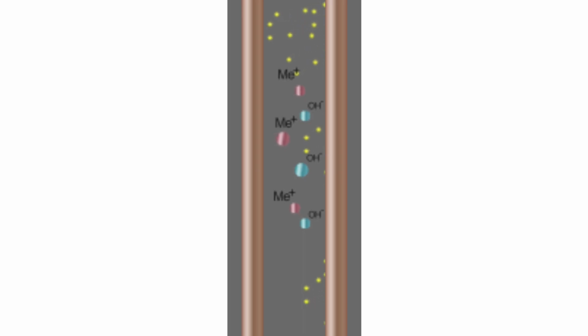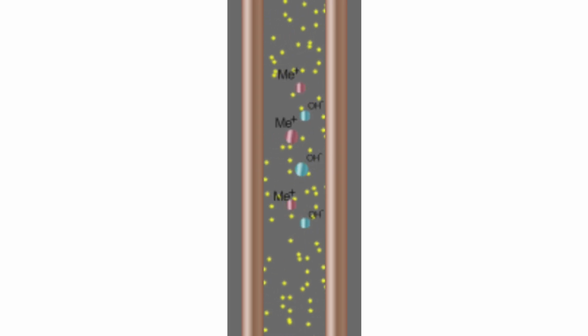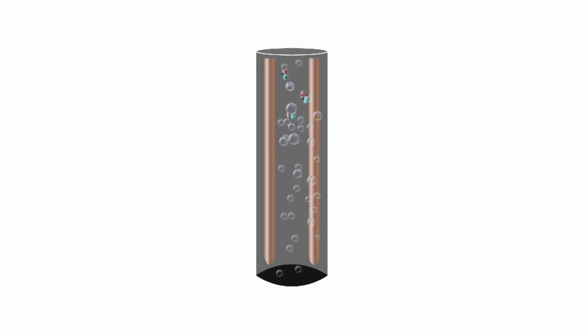Thirdly, electrons flow freely from the cathode to the anode, which destabilizes surface charges on suspended solids and emulsified oils. As the reaction begins, metal ions form complex ions with hydroxyl groups and create large flocks that include metals and other contaminants. Suspended solids and emulsified oils are radially entrained within the flock because of the destabilized surface charges. Finally, the hydrogen gas bubbles help to separate and leave the flocks. These cooperative reactions are what make the EC process so effective and efficient.